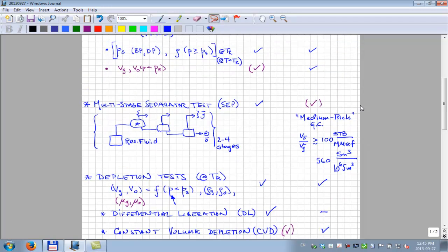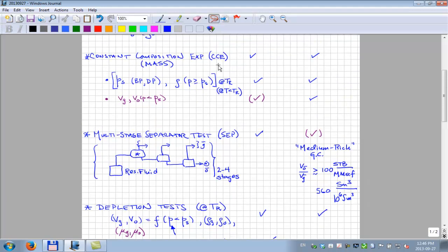So this is giving us the entire suite of conventional laboratory tests that will be made. So the first one is the constant composition expansion. It's primarily trying to give us information about what pressure do we start seeing two phases, okay? What are the densities of the single phase mixture, and possibly it may give us some indication of the amount of phases below the saturation pressure.